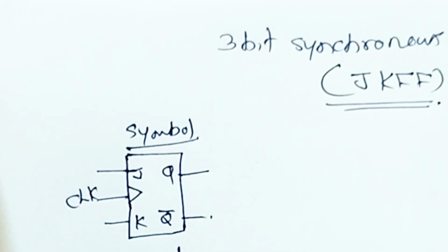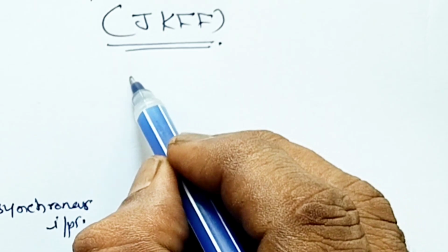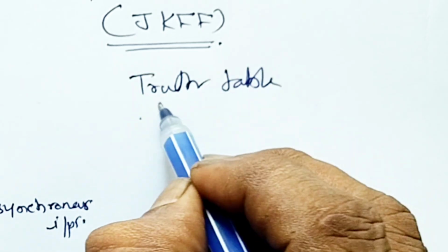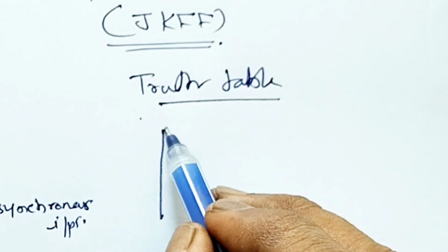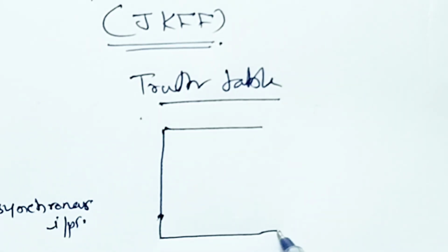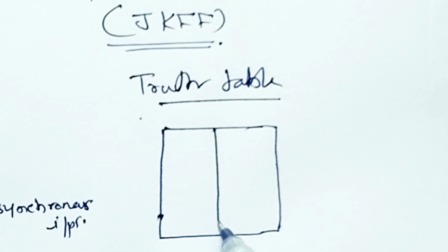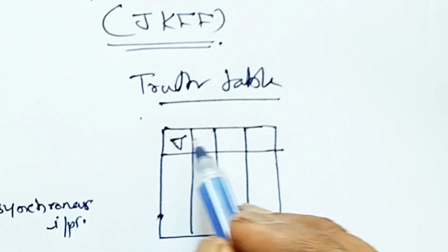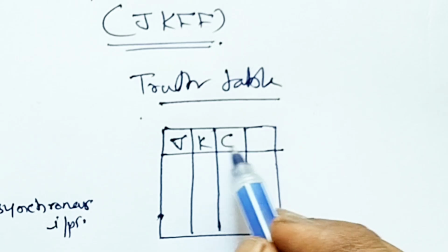They are asynchronous inputs. They are basically used to change the normal flow of counting sequence. If clear is activated for a particular flip flop, then its output Q becomes 0, that is, it is in a reset state. And if preset is activated for a particular flip flop, then its output Q will be equal to 1, that is, it is in a set state. And we can combine all the presets together and clears together. Then we can have the entire control of the counter, and thereby we can change the normal sequence of operation.